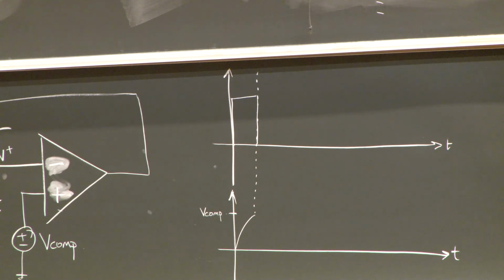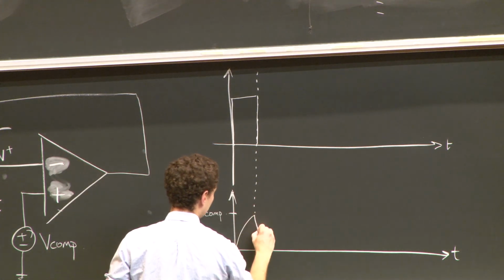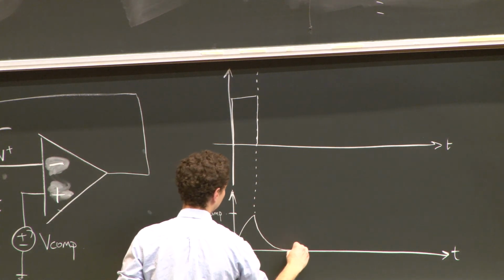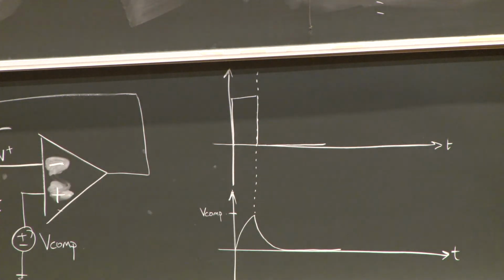This one is going to go the other way to compensate. So it's going to keep going down until it reaches 0. And the output voltage will just stay at 0. Bummer. Okay, so we were close, right? We saw it at the beginning, but it didn't quite work out because we fell below this comparator voltage.